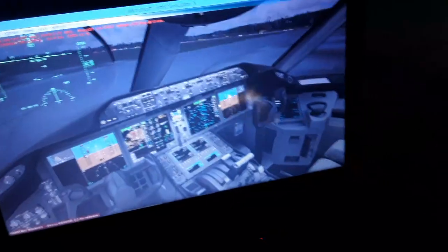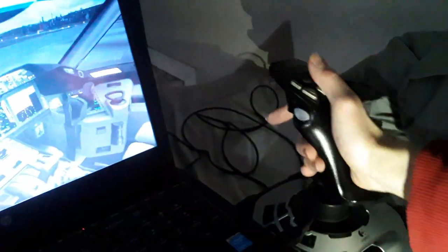Also the attitude of the aircraft in flight will change. So the center of gravity is recalculated automatically. We don't need to do anything. It's calculated by the computers of the aircraft. We also use it for the flight control computers and the autopilot flight director system panel. Also, when we fly the aircraft manually, there is no difference from the autopilot, we have balance of the aircraft in the air.